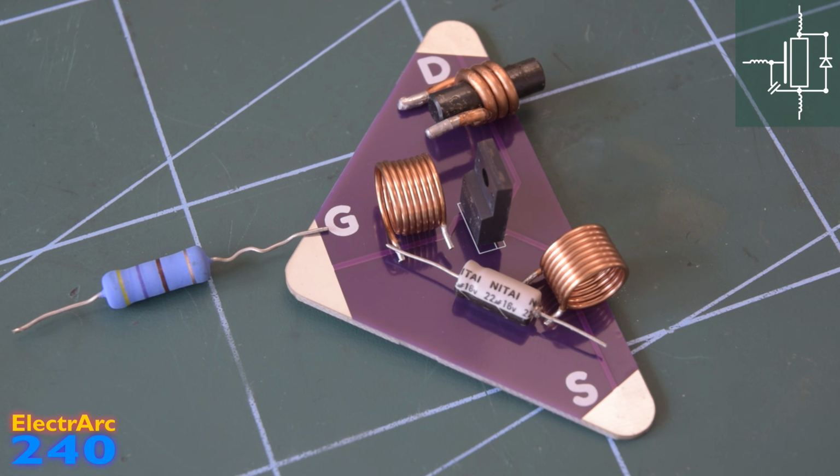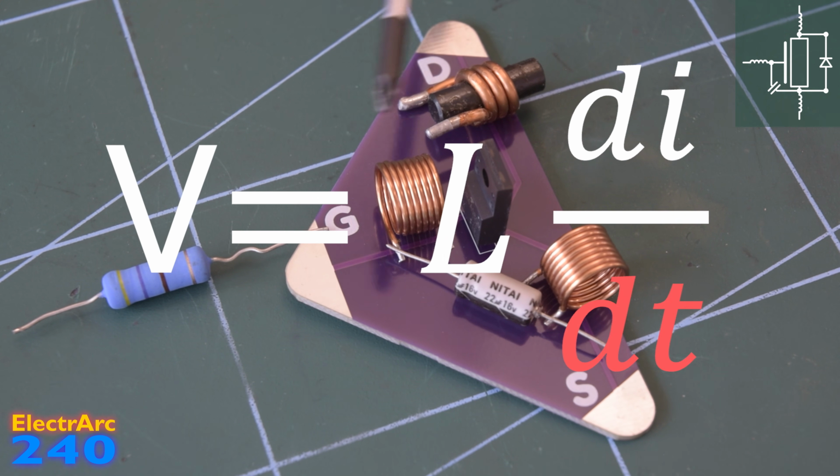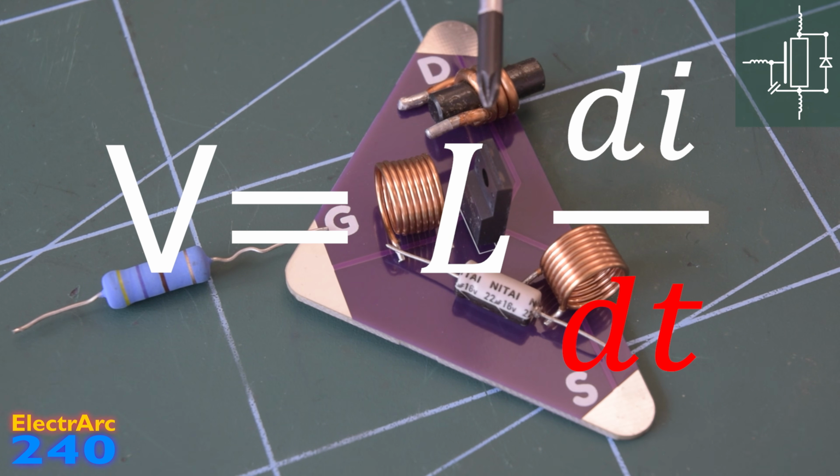Interestingly, we can actually control the overshoot generated by the drain and source inductances, again using the gate resistance. This is because by increasing the gate resistance, we slow down how fast our MOSFET is switching, which reduces the rate of change of current. We're switching the same current, but in a longer time. And as our equation for inductor voltage shows, if we increase the time we're spending changing current, the voltage we generate will be lower.